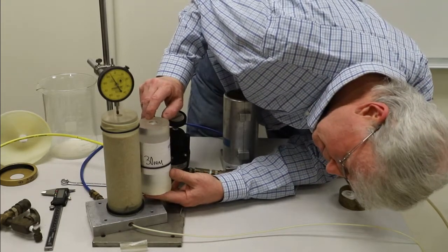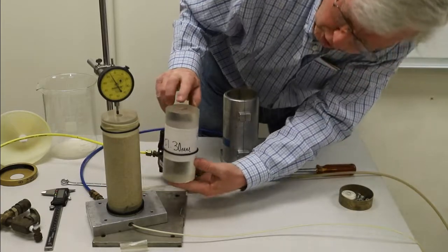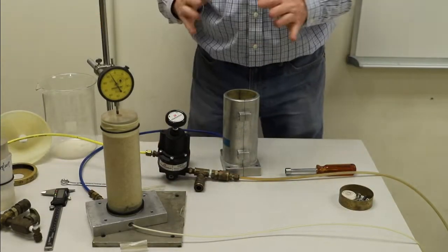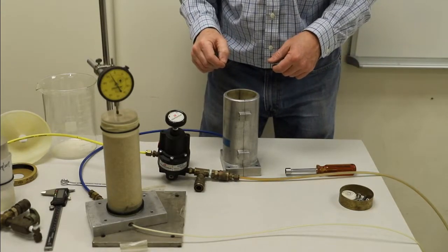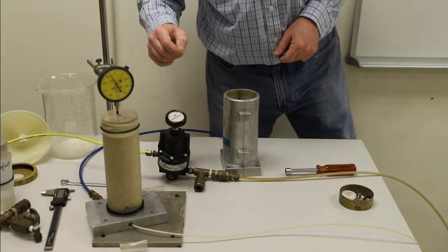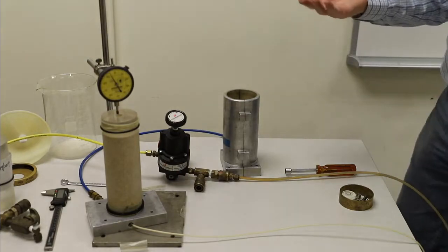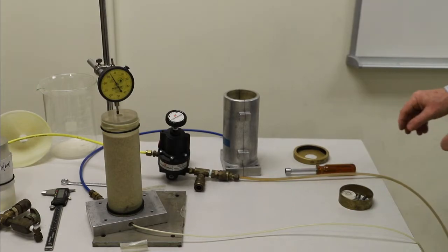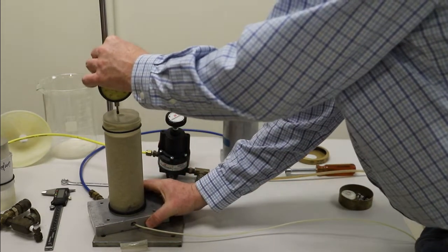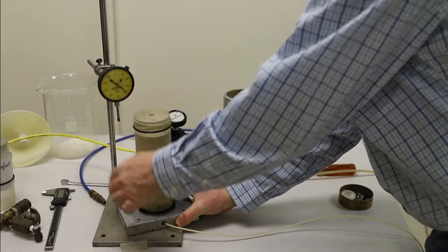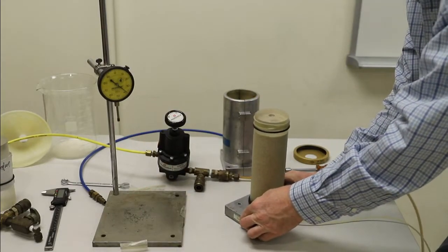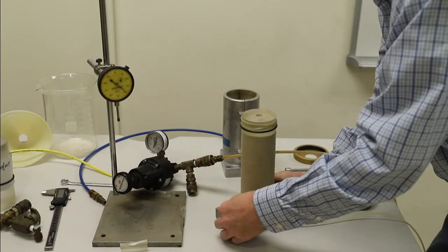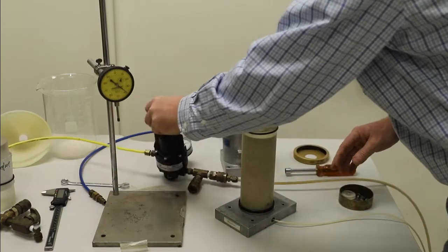It looks like our specimen is a little bit taller than the reference specimen, okay? But with each test, that's going to be a different number. And so that's going to allow us to precisely calculate the height of the specimen, H0. Now we can move the specimen again onto the tabletop. We're going to do one more measurement because we need to know the initial diameter to calculate the area.